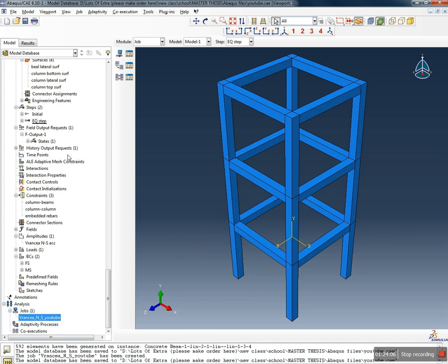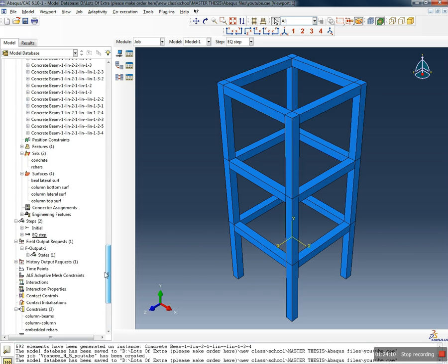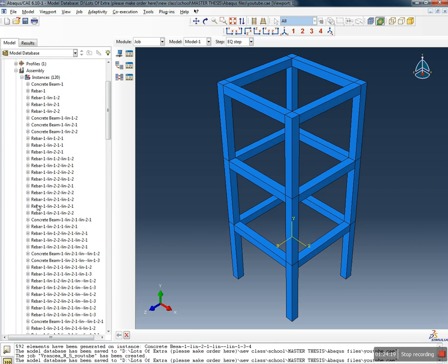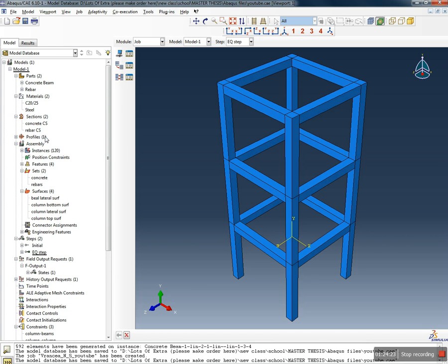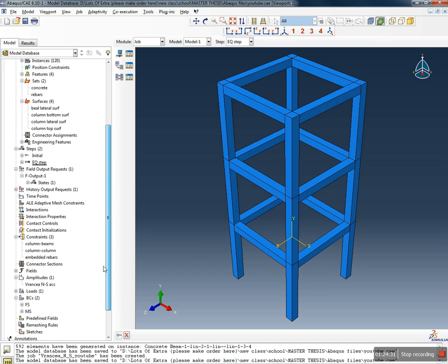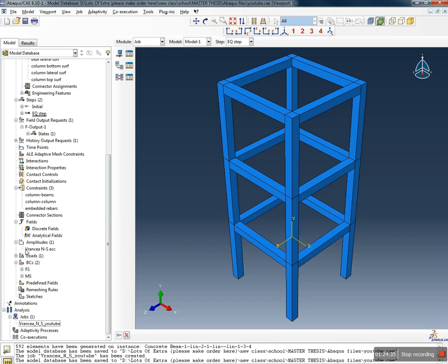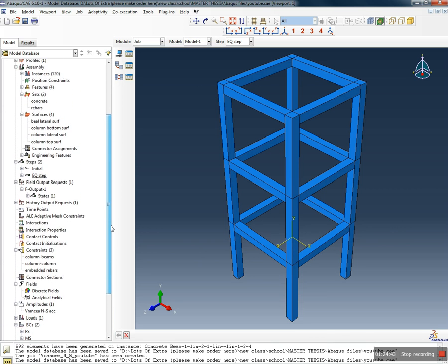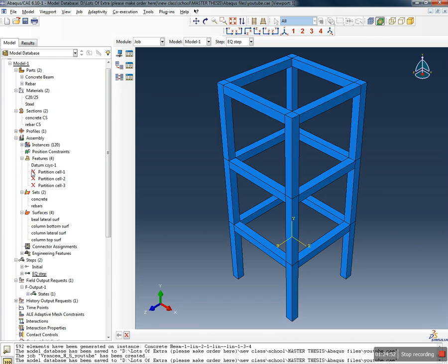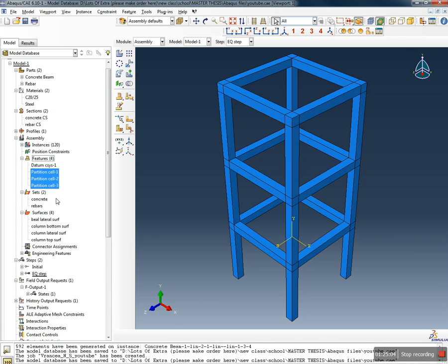So what I want to do is go to my partition planes, which were somewhere here. They have to be somewhere here. Just go to position constraints. I know I had some problem finding them at some point, but they are here somewhere. We will find them. Column. Feature. Okay, you see here you have features, and these little bastards here, they were suppressed, so we will just resume them, and now it's much better.